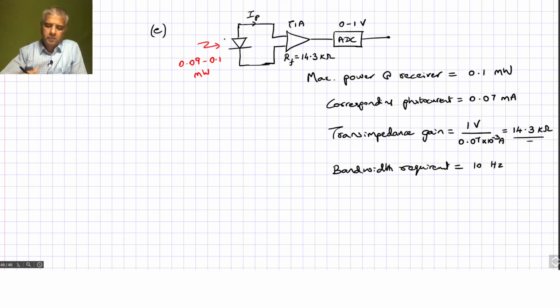Then, while it's getting amplified, it will accumulate thermal noise in the receiver, and the op-amp, whose noise characteristics we just saw, will also contribute to the noise. So those are the major noise sources, and of course we can also have quantization noise in the ADC. Let's just neglect that for a second, and let's look at all these other noise sources.